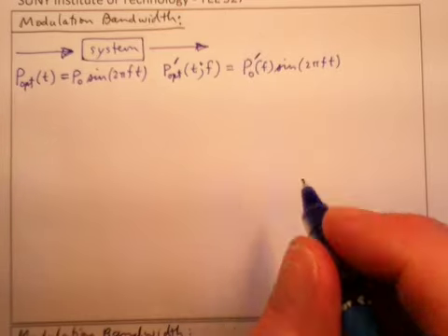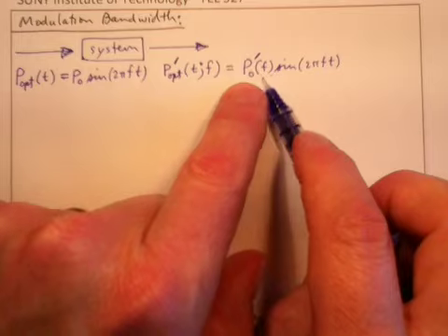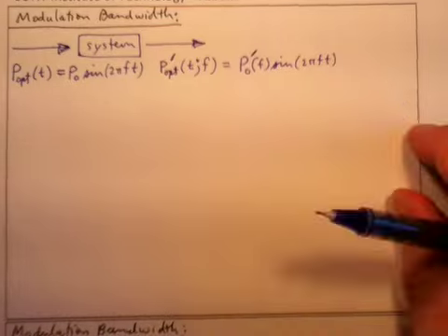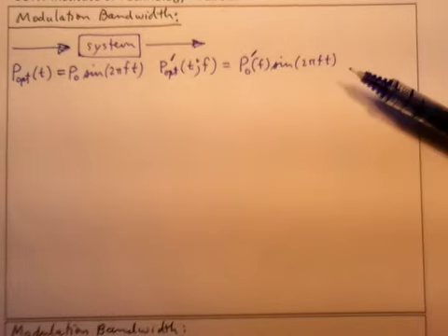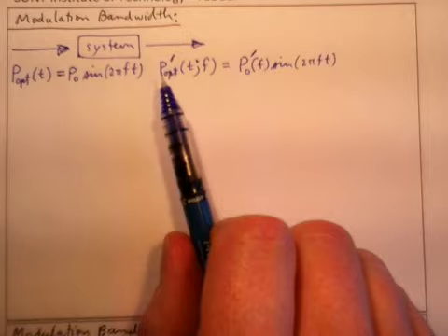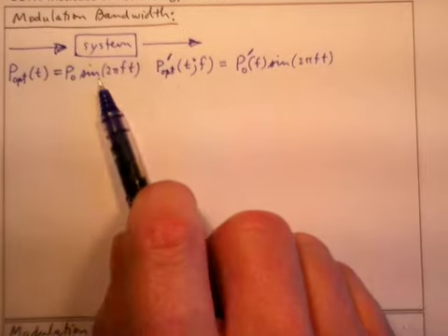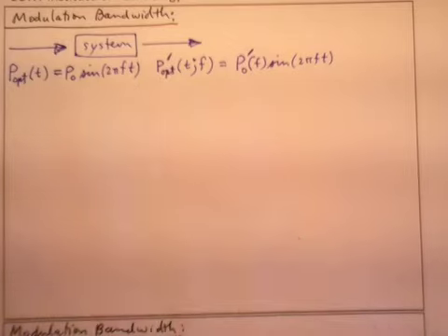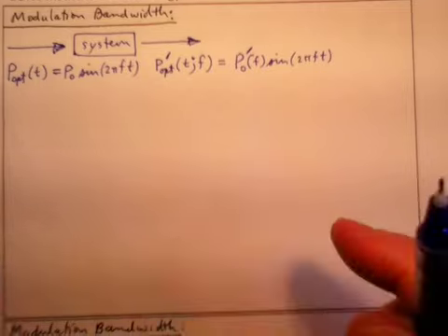What we're going to find is that the output does vary with the frequency, and I've got a spreadsheet that I'm going to go ahead and post that demonstrates this in the terms that we've already seen in terms of pulse spreading. What we see in our system here is that if you have too high of a frequency going in, pulse spreading is going to spread those pulses out, and they're going to be overlapping with one another, and that's going to give us an upper limit on the bit rate of the system.